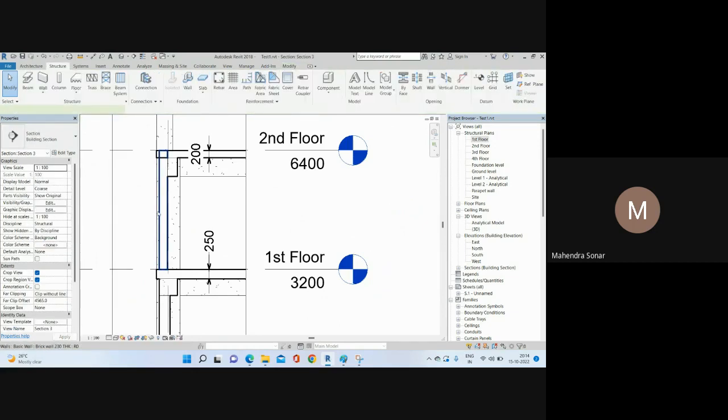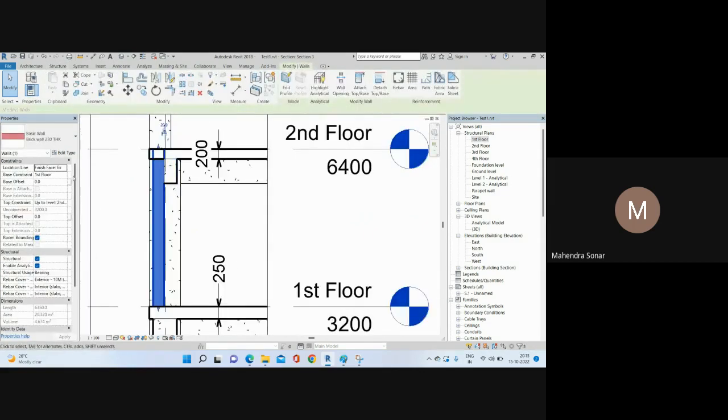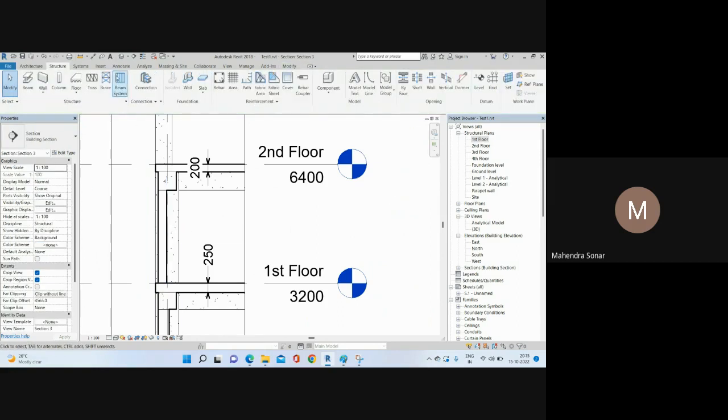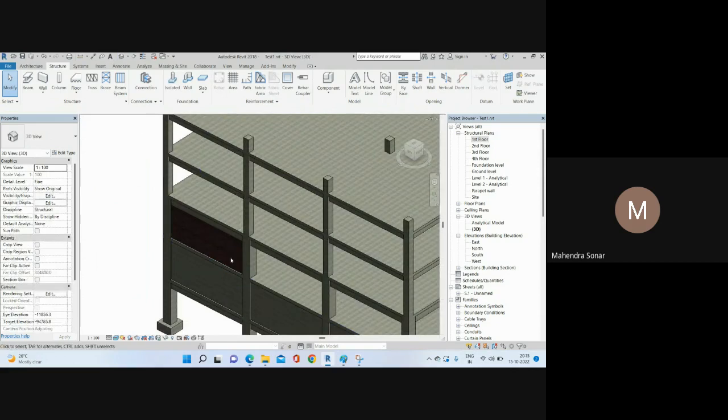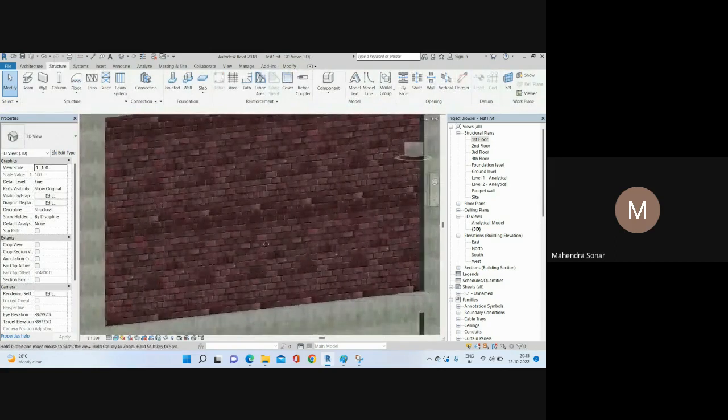like that. Okay, but I want to stop this brick wall below this beam. So we know the differences. So I will add here minus 700. Oops, I have given the wrong. Okay, in top constraint. So give the minus 700, like that. Okay, so if you look at in 3D view, so you can see what your brick wall looks like. Can you see this? Yes, sir.